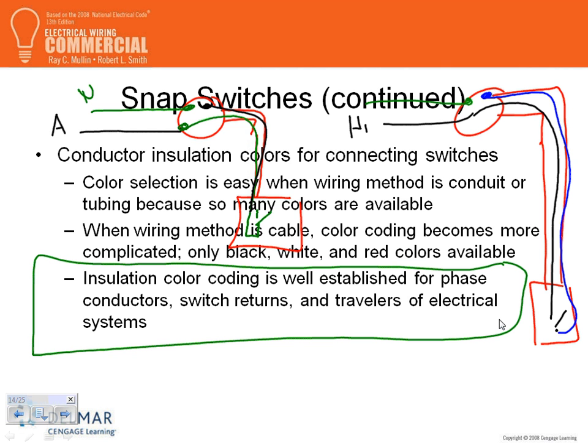That's on the test tomorrow, guaranteed. The white conductor or the gray conductor is going to be the one that brings the power to the switch. The switched leg has to be any other color other than white, gray, or green. Very important. So this color here, in this combination, has to be a white. This color, black. And of course, this color is white. I identify it, and this color, black.